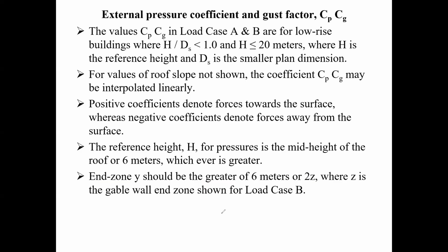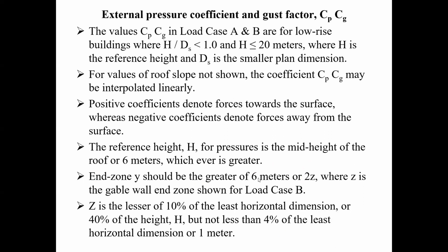Or what they also say, if you want to be conservative, you can go up to where your first frame is. So if we have our spacing here of 5 meters, you're allowed to go up to 5 meters where your first frame is, and so on. But I believe I took 6 meters to be on the safe side.